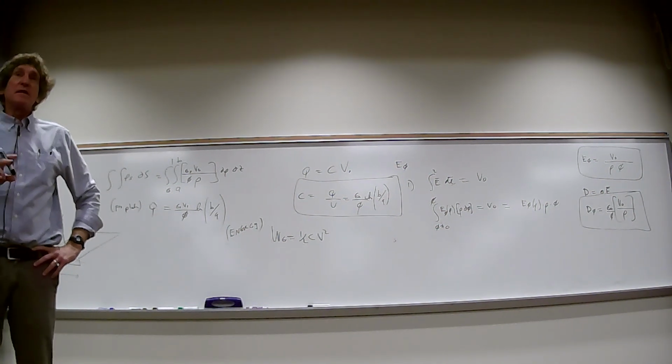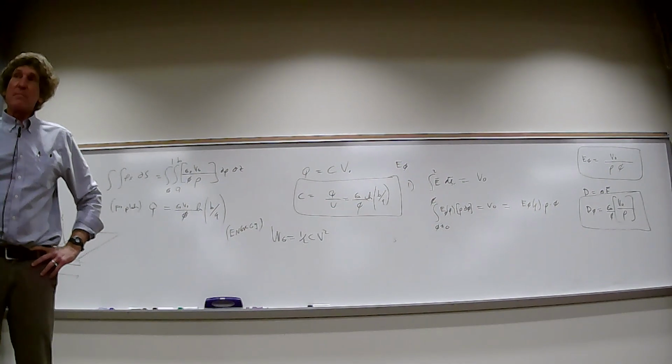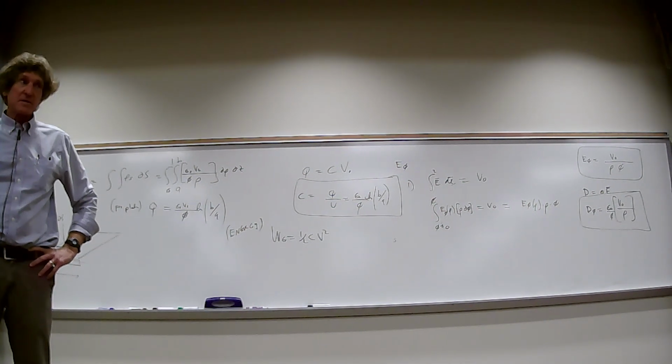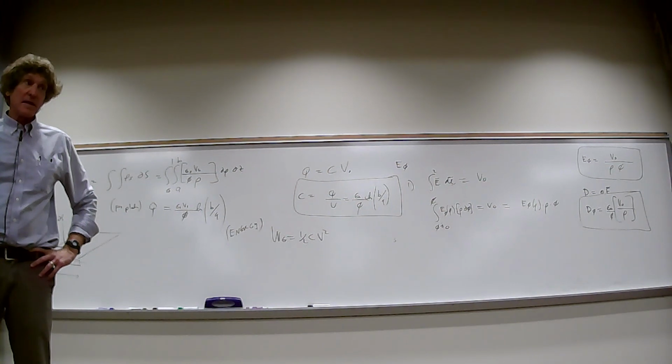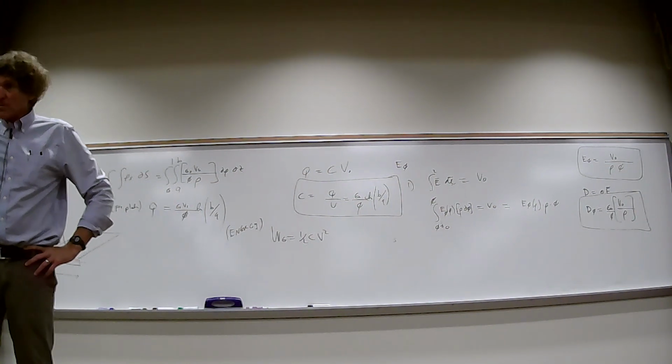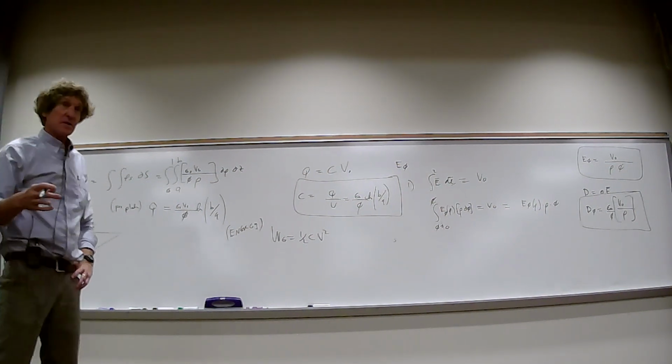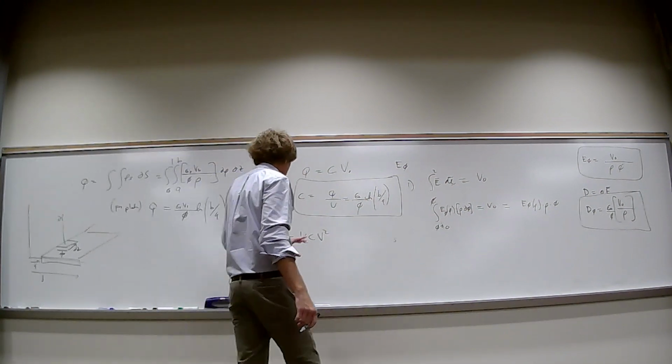You'll notice that the energy is directly proportional to the amount of capacitance between the plates, but it's also directly proportional to the square of the voltage. What that means is, if you double the voltage, you increase the energy by a factor of 4. Y'all follow me, class? It's real important that you understand this basic relationship.